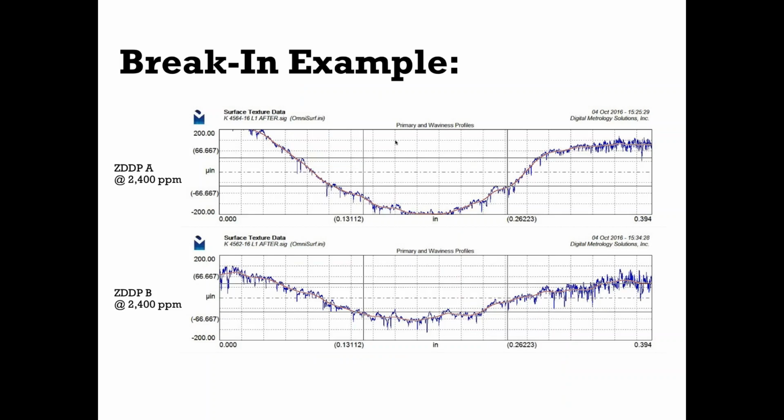Just to give you a quick, real-world example. What you're looking at here are the Zeiss profilometer results from two different cams, both the exact same cam grind, measuring left to right across max lift. So if you can visualize taking the cam, holding it in this position, this is lobe 1, so on a small block Chevrolet, that is exhaust number 1. And so you rotate the cam till it hits max lift. You can use a profilometer to go left to right, and that measures the contact patch, the wear scar, if you will, across max lift.